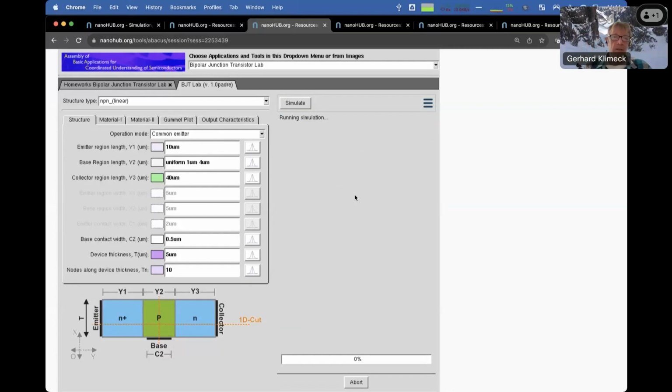So in an ideal sense, you would look for a beta at a certain current, right? And look at beta as a function of sweep, or the maximum collector current at a certain bias. So you just home in on one current output, one number, so to speak, and then you can get better distributions.